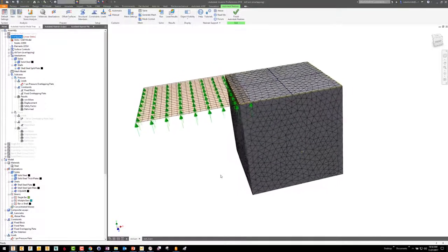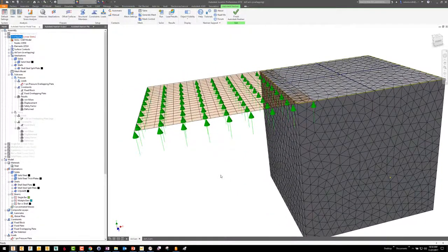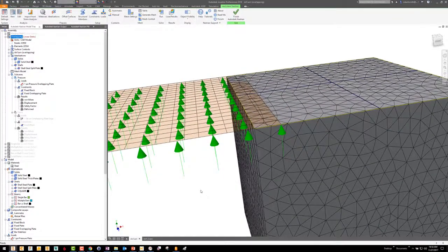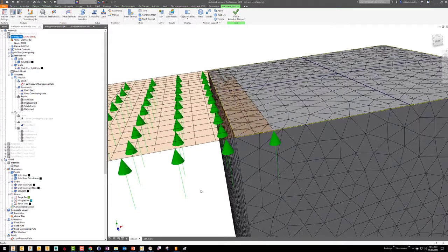But look what's been done here. A lot like the second model I did, where everything's meshed in the same way, shell, solids. I do have a fixed condition on the end of the shell, right? And the two parts are bonded together, and there's a pressure on the underside of the shell. But in this case, the shell structure is overlapping the solid structure such that they're not meeting at a single row of nodes, not a single edge. So there's at least 2 rows of nodes, or at least basically three nodes that are not in a line connecting these two parts together.